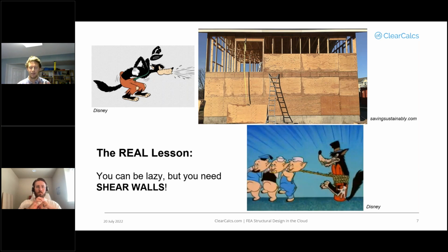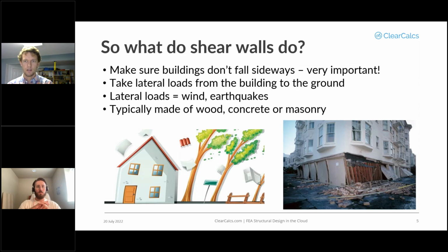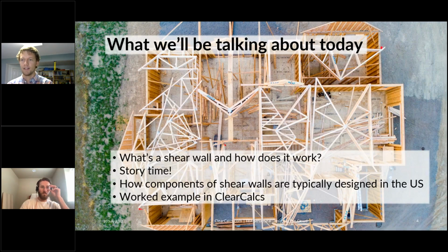I hope that I made it clear. You're making me regret not having a top-down view of a shear wall now. Maybe we can see it here where if the wind goes from left to right in this case, it's going to be hitting the walls that are going up and down, and then getting transmitted by the floor into the walls that are going left to right.